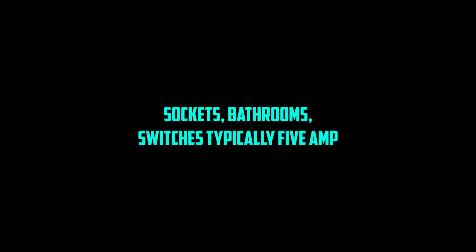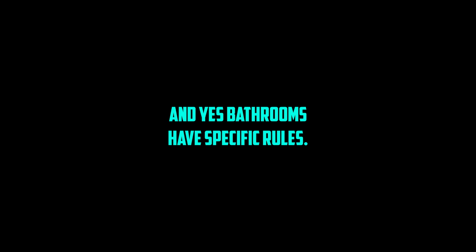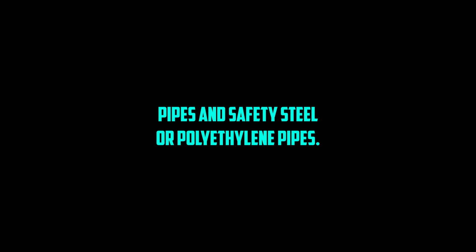Switches typically 5 amp rated for lighting, lamp holders, and yes, bathrooms have specific rules. Pull cord switches must be used to avoid touching switches with wet hands. No standard sockets allowed either, only special shaver sockets. Gas supply, pipes and safety.